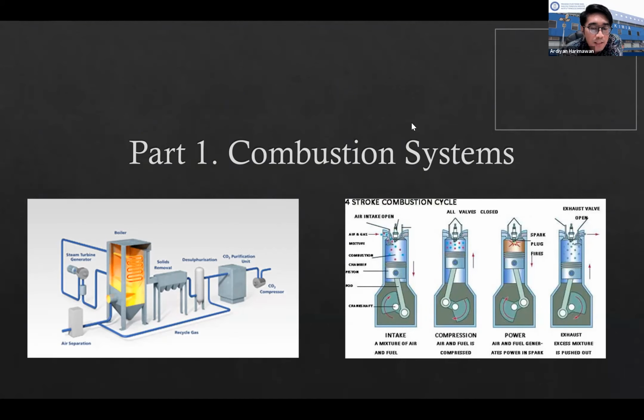oxygen. That's why in combustion, if you want complete combustion to occur, then you need to provide excess air. You still remember, right? Yes, sir. Okay. So if you do not have excess air, so maybe you have less air than stoichiometrically required, what will happen? Or we call it incomplete combustion.